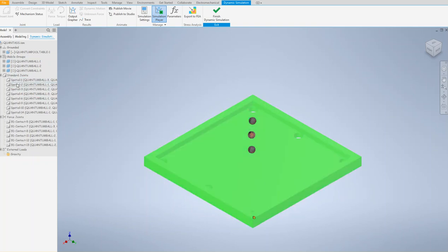The first relationship, between the balls and the billiard table, is called spatial relationship. And finally, you need to establish the contact type of relationship between the quantum balls. Once you accomplish that, you need to position the balls, of course, and make sure that the table is also grounded and the balls are not grounded. All right, and then we're ready to quantum play.